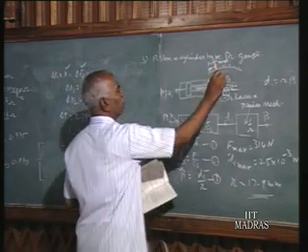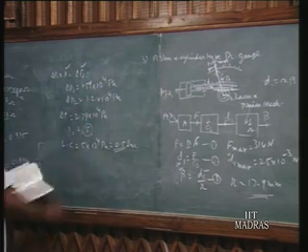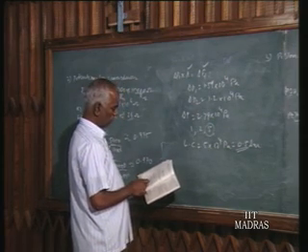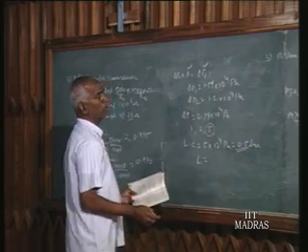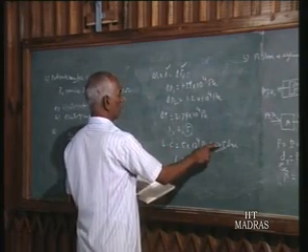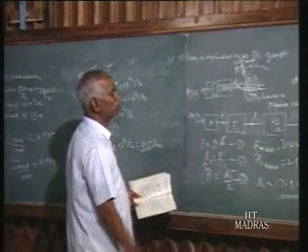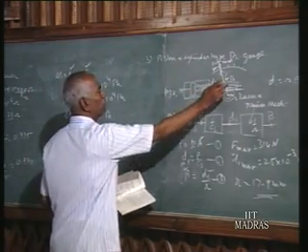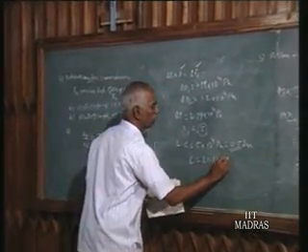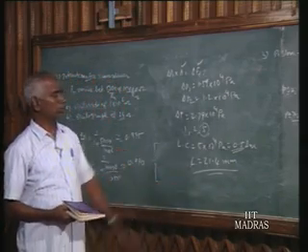If it is 1.5 mm and L is the length of the pointer, we should know what the length L should be for this least count. So if you consider this delta P as 0.5 bar, for 0.5 bar you can get what the rotation beta should be. For the whole instrument you can get the gain. From the gain we know, for the 0.5 bar input pressure, what beta should be. Then L into delta beta is equal to our length. So L comes about 21.4 millimeter. Converting this least count in terms of beta, the output angle, we can calculate this L. This we can cross-check.